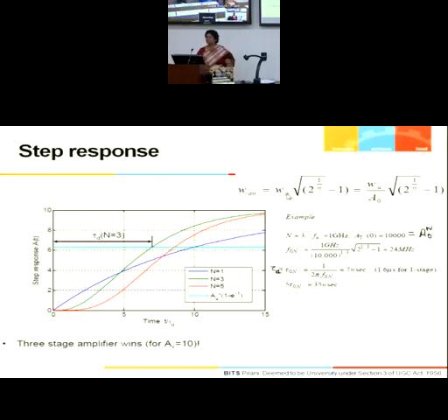Understand? So omega naught for the 3-stage series. Okay, I use this expression. But you are given a unity gain bandwidth. No, A total is given. So A naught to the power n is given. A total is given. So this would be A naught, which is 10,000 to the power 1 by 3. 1 by 3 because it is a three stage amplifier.